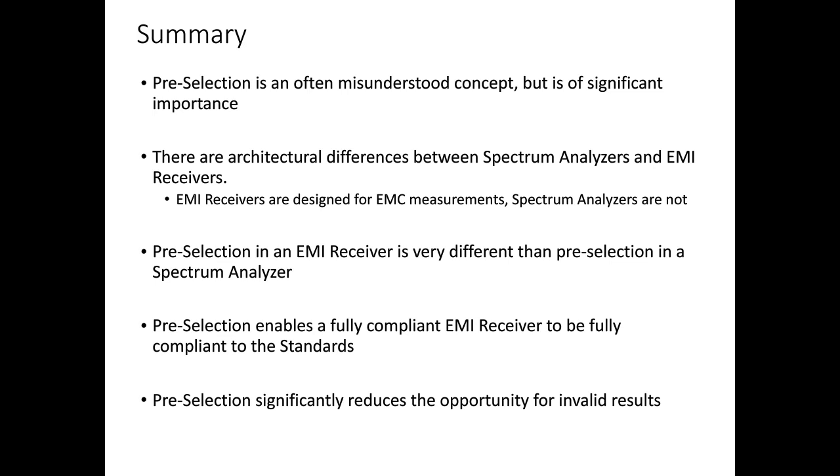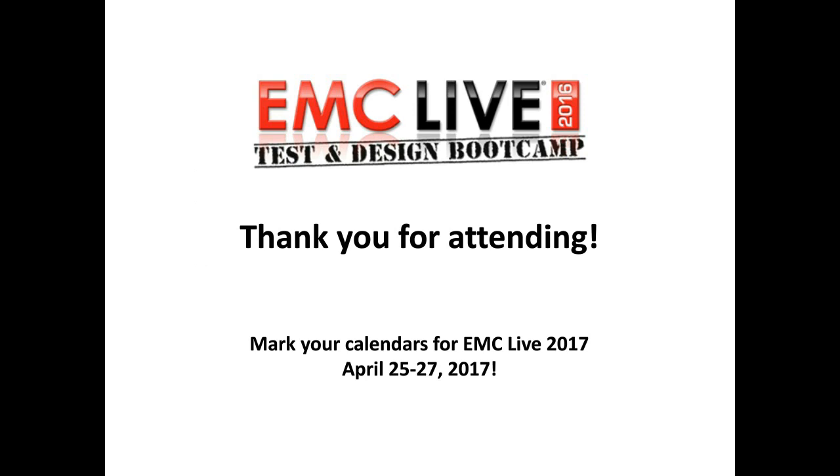Pre-selection enables a fully compliant receiver to be fully compliant to the standards. Without pre-selection, a fully compliant receiver could not be fully compliant. And then again, one of the main themes here is that pre-selection significantly reduces the opportunity for invalid results, which is the point of pre-compliance and obviously full compliance measurements. But in a pre-compliance application, you want to do anything you can to make sure that you have a high degree of confidence in your measurements. And with that, Ken, I'll pass it to you for questions.